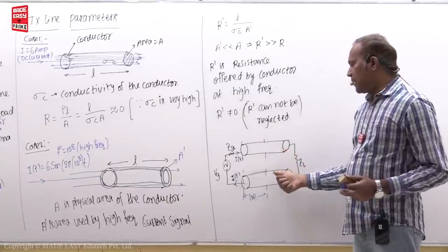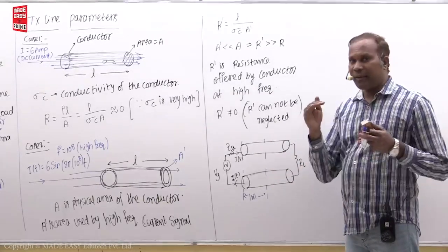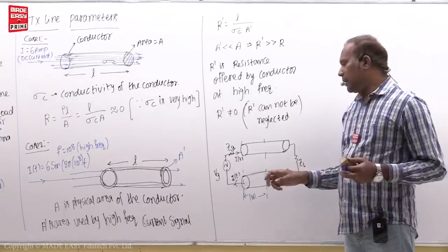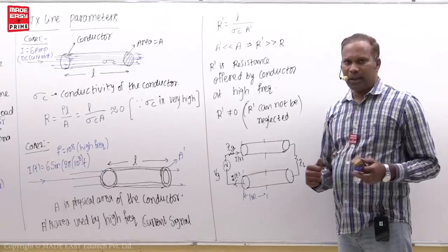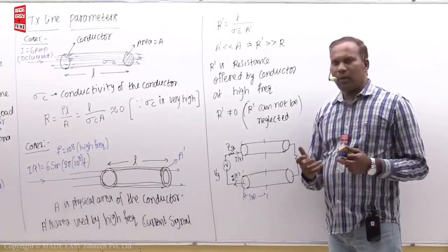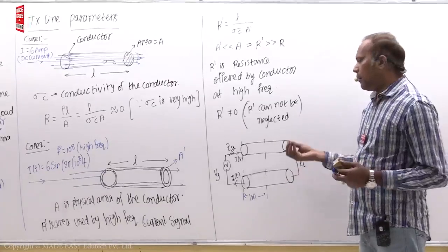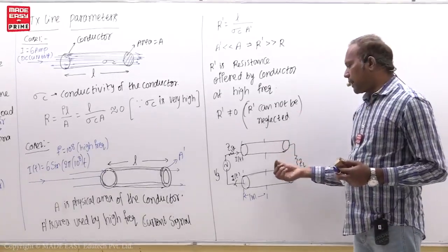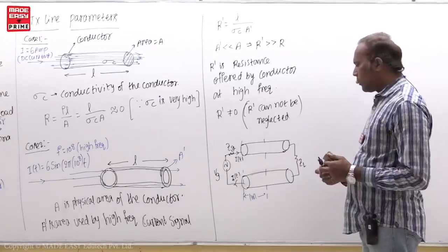When these transmission line conductors are manufactured, they do the experiment at a particular frequency, and on the data sheet, they print that information. So as an engineer, you can go and see that data sheet, and whatever resistance value the conductors require, you can pick up that one. That is the practical aspect, which is not needed now.